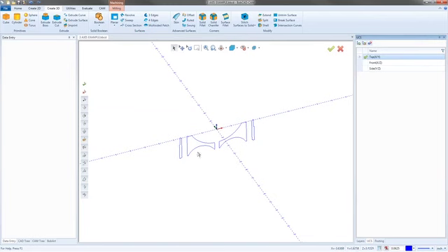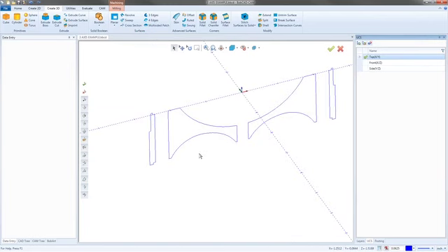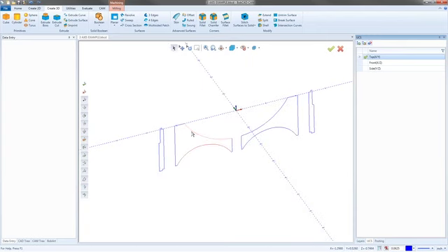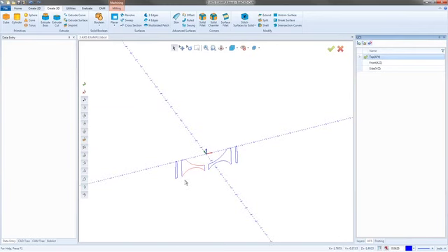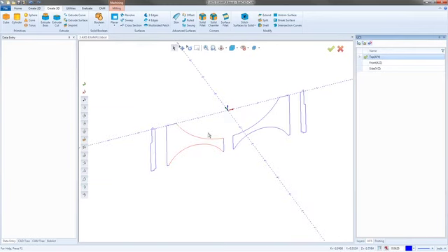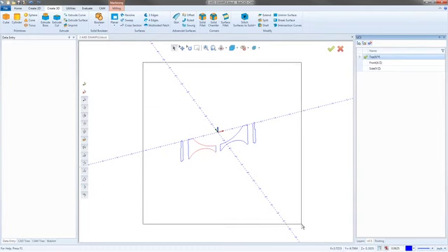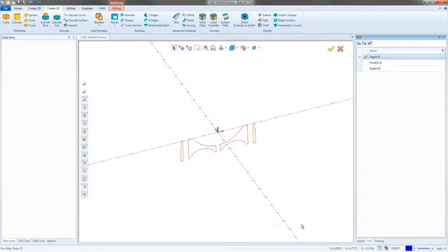So now with this piece of geometry, we actually have a lot more than I need right now. All I need is this arc here and this line right here. I'm going to take these lines and revolve them into a solid model, and when I revolve them into that solid, it's going to give me a new surface. So I've selected the two I want to keep, and now I'm going to drag a box over the entire set of lines. That'll deselect what I had selected and select what I didn't. And now I can just delete that stuff.